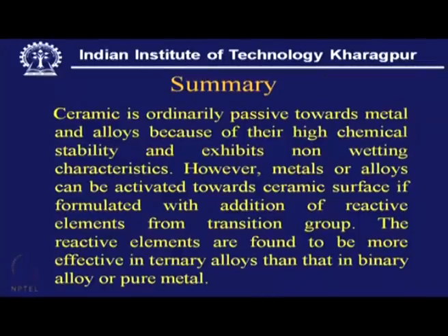However, metals or alloys can be activated towards a ceramic surface if formulated with the addition of reactive elements from the transition group. The reactive elements are found to be more effective in ternary alloys than in binary alloys or pure metals.